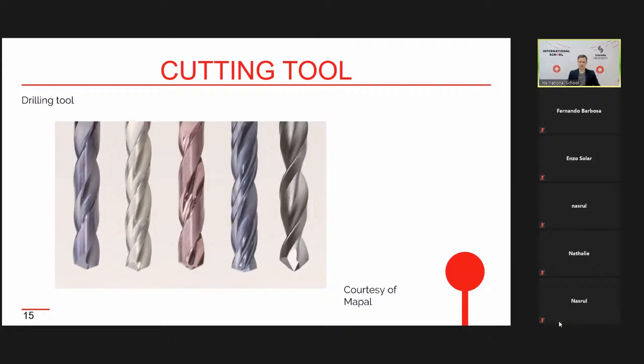This picture shows drills that are used in the metal cutting industry. You can see different cutting tools in different drills. And what is the difference? They are all for metal cutting operations. But this drill on the right has a flute. This is the helix flute of the drill. This drill is used for soft materials, when the chip is relatively bigger than for other processes.